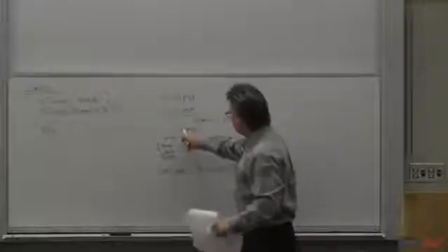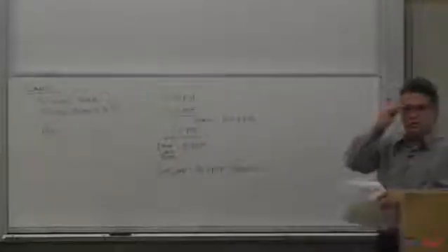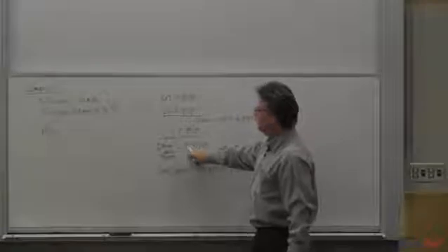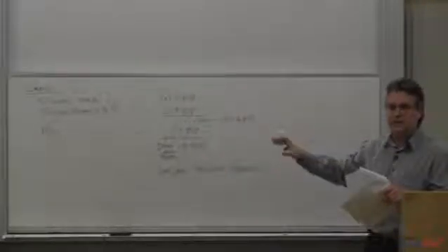We always throw in something for a little extra, little conduit, little plumbing, little something that we can't anticipate. I've put in 2 pounds a square foot. I've told you whatever it is I want you to put in on yours, 2 or 3. So the total dead load is 91.4 pounds per square foot. That comes from the system itself. Dead loads, you have to calculate whatever it is you actually have.